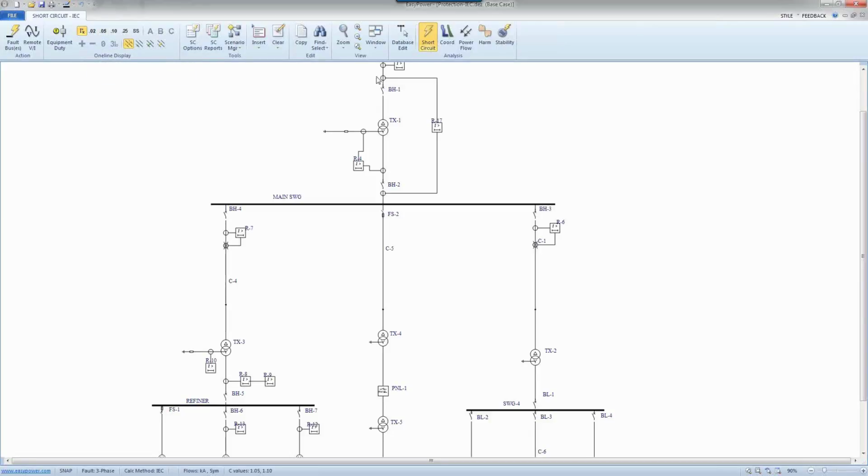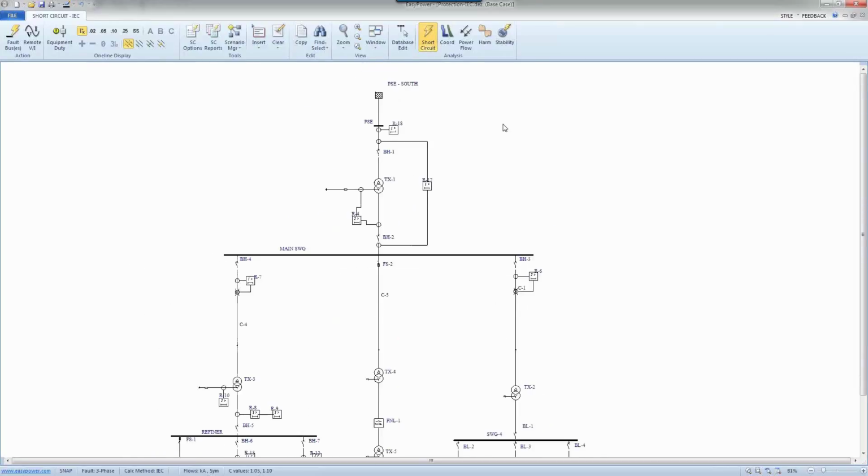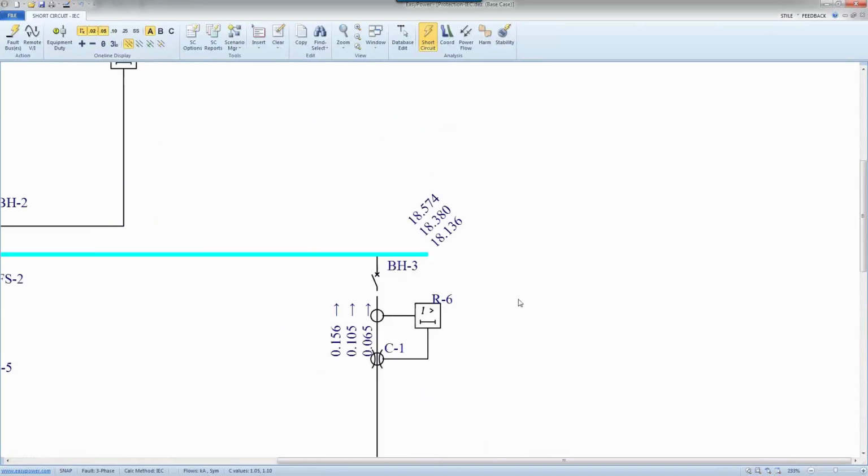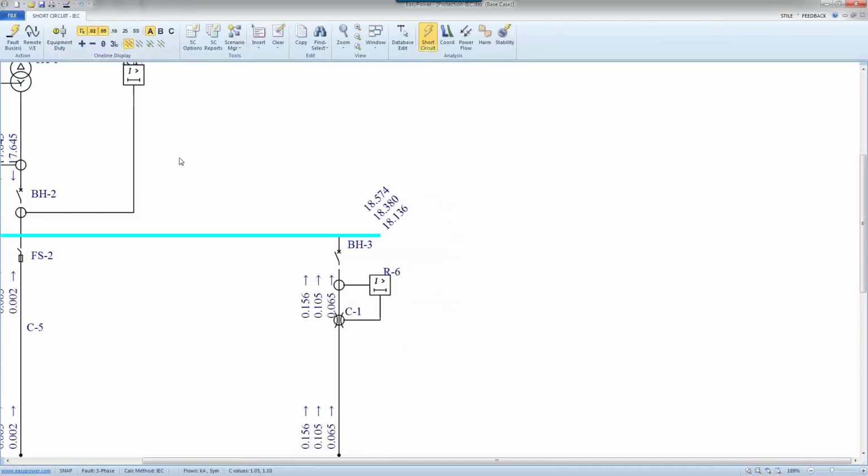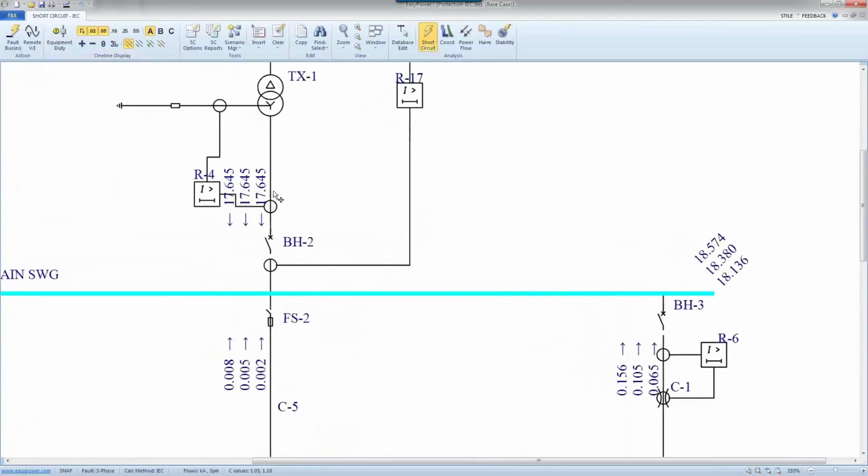So logically, you would imagine, and let's just run a fault here. If I run a three-phase fault here and start showing the values, let's say breaking 20 millisecond, breaking 50 millisecond, as you see, the current starts decaying, and it would make sense. That's the initial value. The breaking currents, you would expect them to drop. And again, you see that I'm very cautious using this terminology. That's not always the case, as you see.